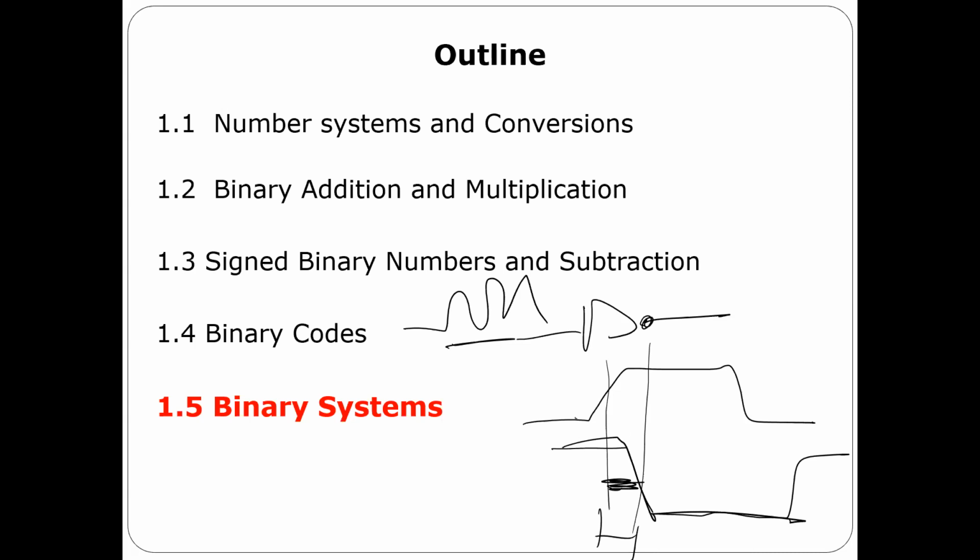You got what I'm saying? So this delay puts a restriction on the maximum frequency. At least I have to make sure that before I give you the second pulse, you have already finished the first one. Very simple. I also want you to do some search about these basic things, about the relation between the delay, propagation delay, and frequency.